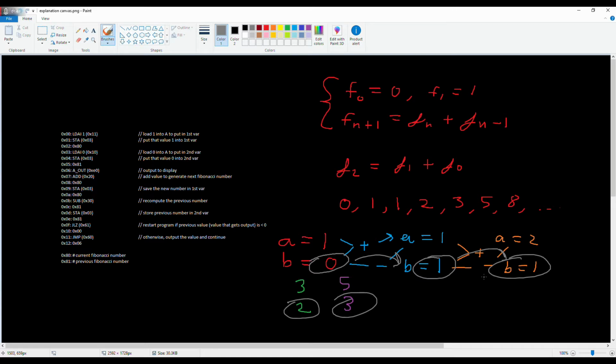And that's exactly what this assembly does here, where we're just going to go through, and in the assembly language, the first thing we do is we initialize our A is equal to 1. Then we initialize our B equal to 0 here. Then the next thing we do is we do our first output instruction. So this is out previous right here, where we output the contents of the A register.